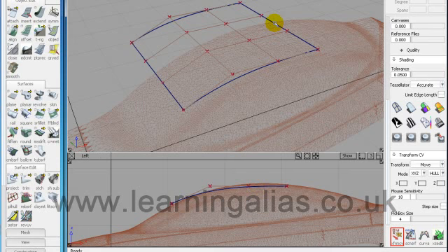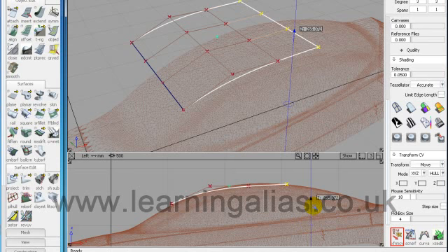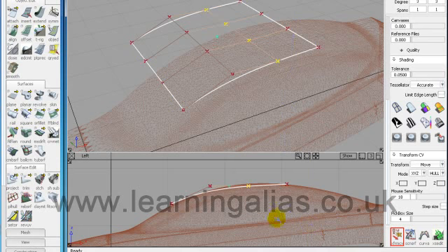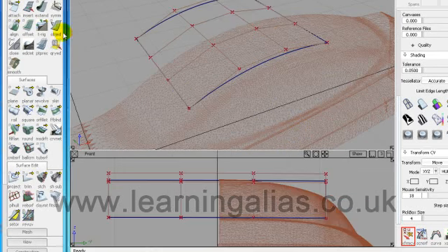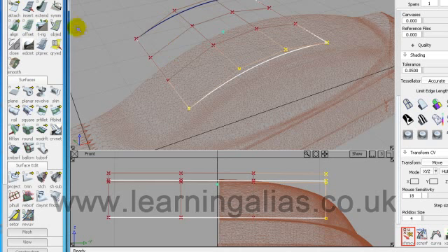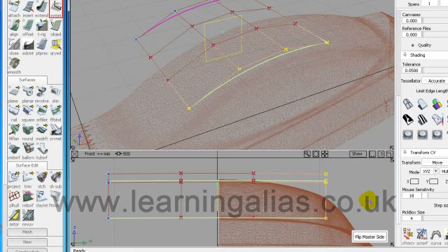So it allows me to pick the hull there and see what I'm doing here, and work a lot quicker like that. So I suggest you do preferences, hotkeys, and set up something similar. Our next job is to pick a hull in this direction, and then we must remember to switch on symmetrical model, and if we don't, then we've ruined our model. Then we're ready to go, and we start.